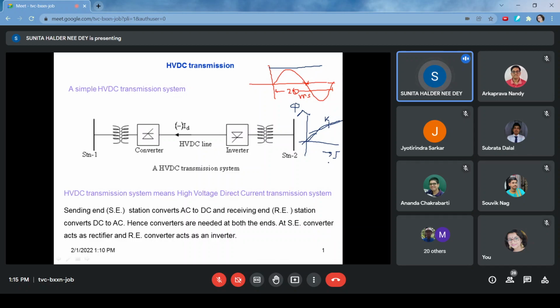So that's why there is non-linearity. The inductance is changing, which means that current will change, or the induced EMF will change. So that will induce non-linearity. You have done the BH characteristics of the transformer in your power system lab in first sem. You have seen there that when the excitation voltage is beyond the rated voltage, the transformer voltage was 110 volt. If we give 110 volt or near to that, then you get some distortion. But near 25 volt or 50 volt, you do not get it.